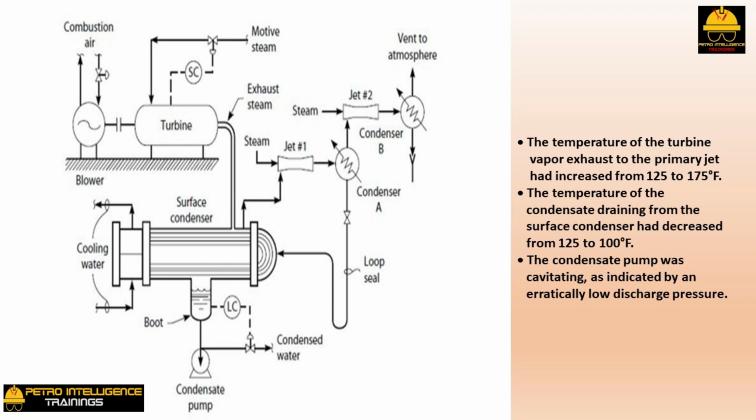The condensate is covering some of the tubes in the surface condenser. This subcools the condensate and does no harm. However, the number of tubes exposed to the condensing steam is also reduced. This forces the steam to condense at a higher temperature. In effect, the condensate backup has reduced the surface area of the condenser available to condense the steam. The higher the condensation temperature of the steam, the higher the condensation pressure of the steam.